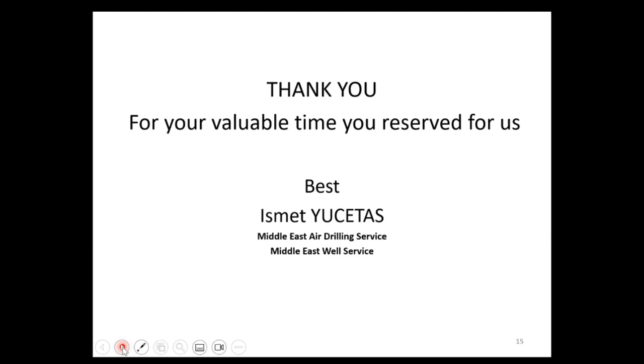Okay. And now the questions are trickling in, so let me see how I can group this in the best way possible. One of the questions here: is there a danger of scaling at the re-injection valve because of the CO2 injection? And that goes hand in hand with the question about supercritical CO2 combined with water being very corrosive. Do you have any experience and comments on that?